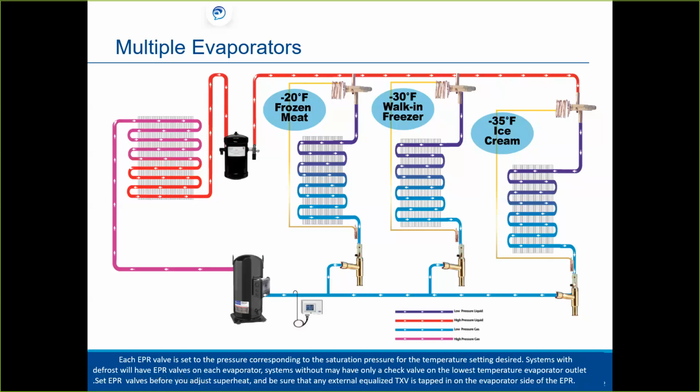Here's that example I was telling you about. You have one set here for minus 20 degrees. I typically in class would have someone pick out a refrigerant like 404A and then take a few minutes and tell me what the pressure would be set at for each one of these, in correlation with the temperatures that we're setting this for, like 404A.